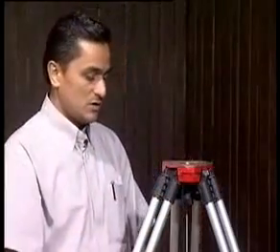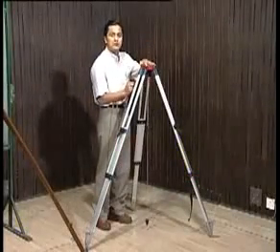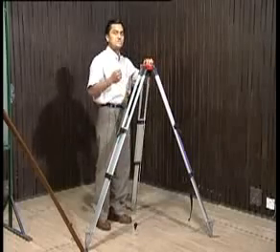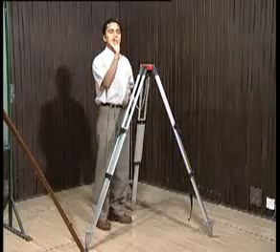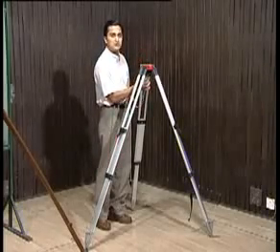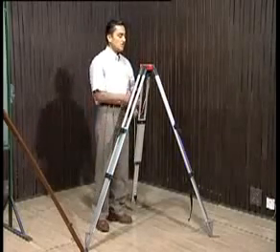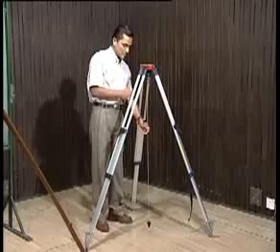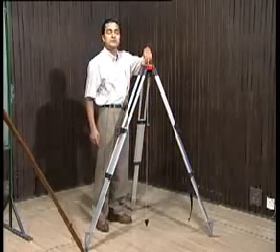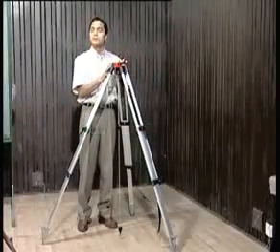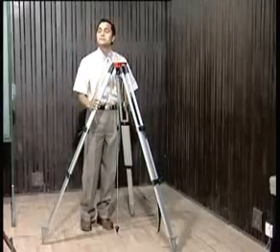The next, what we do, first of all, we center this tripod. How do we center it? We can make use of, if you don't have a plumb bob, you know the plumb bob? If you don't have a plumb bob, I can make use of even a stone. I can drop that stone from the center of the theodolite, whether it drops nearly around that point in the ground or not. If you have a plumb bob, I can suspend this plumb bob like this, and it will tell me whether this particular point is exactly over that point or not. So all these things can be ensured. Now having done this, because this is approximate centering, it's not exact centering as yet.